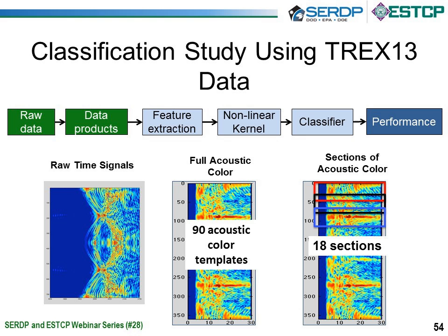However, if you remember in the T-Rex experiment, we actually used a linear SAS system. In the interest of time, we didn't go through the details of how you build an acoustic color template, but the idea is that you would put a target out, have divers manipulate it, run the linear rail to acquire a section of linear acoustic data, have the divers go out and manipulate the target, and run your linear rail again. In that way you can stitch together this full acoustic color response. So if you already had these linear rail sections, why not just use those?